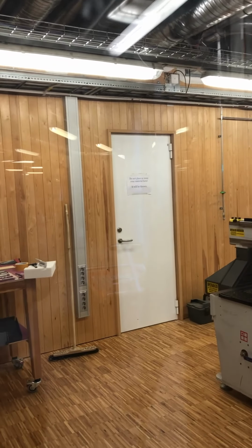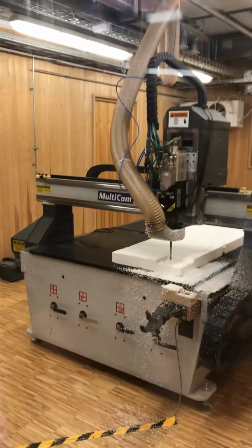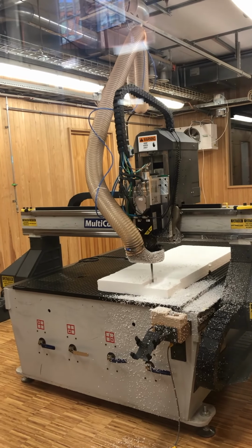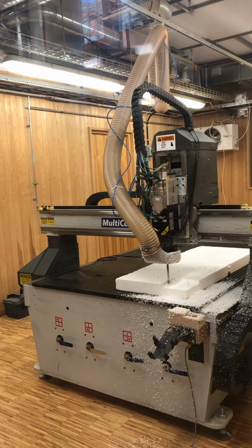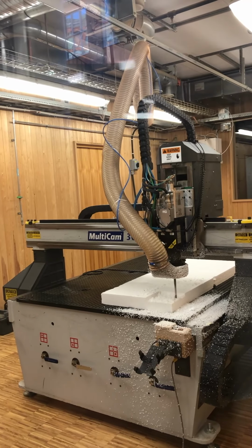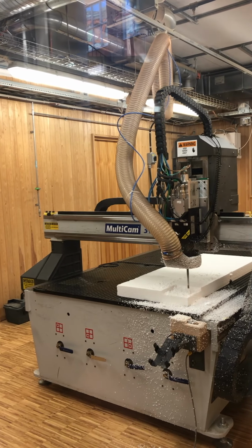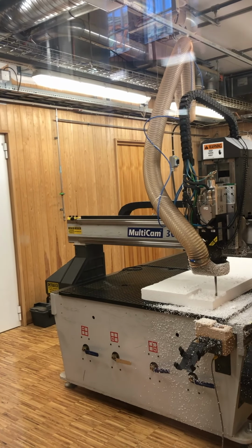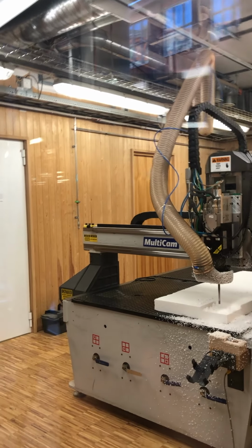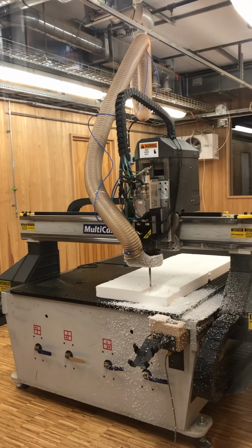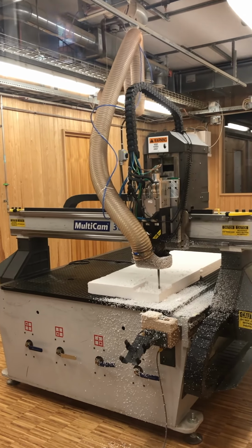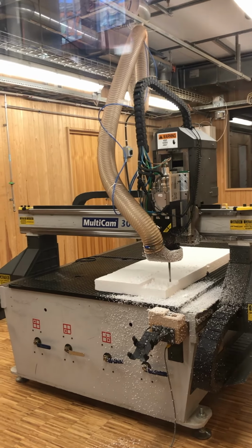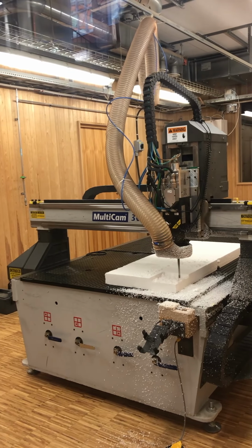Yeah, the wider the diameter of the bit, the more surface area of the material it can cover in one go. Because if you're going for a thinner diameter, then it has to backtrack several times to cover the same area. So one is time. This one, the preview said, I think, 17 minutes, which in real time can perhaps be 20-25 minutes. And if one would have half the diameter, I don't know if it's proportional, but I would guess that it's double the time.